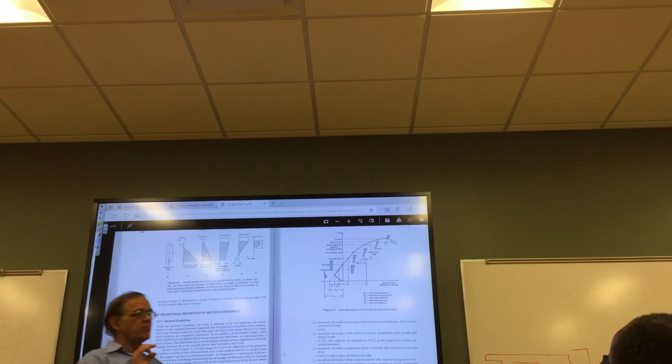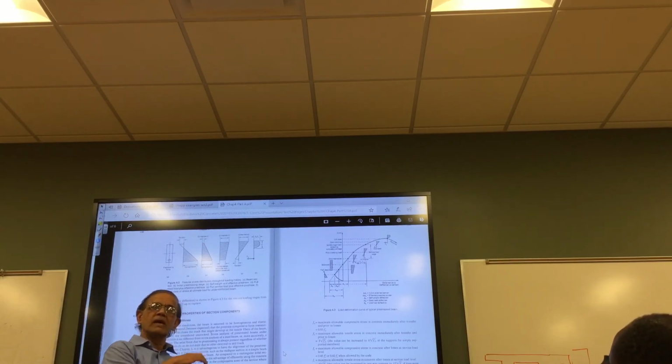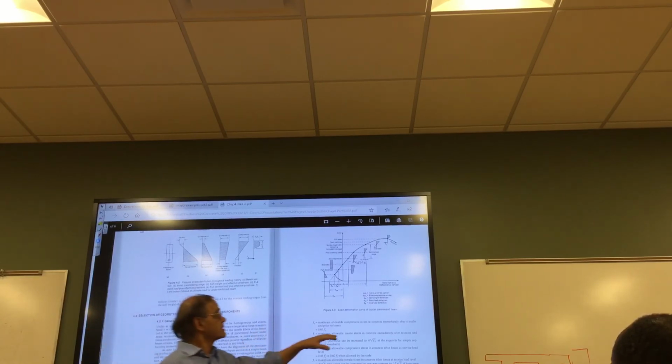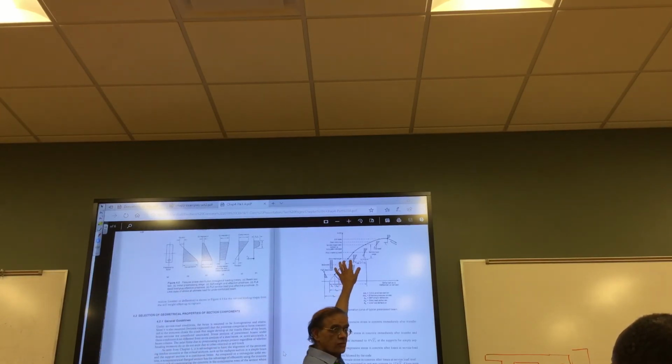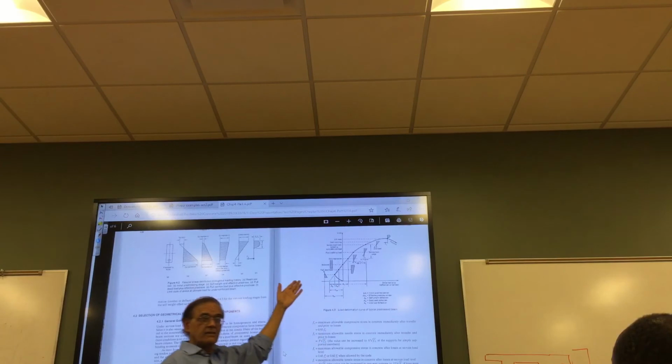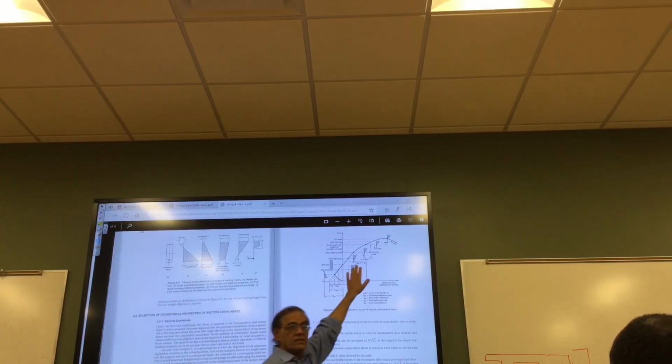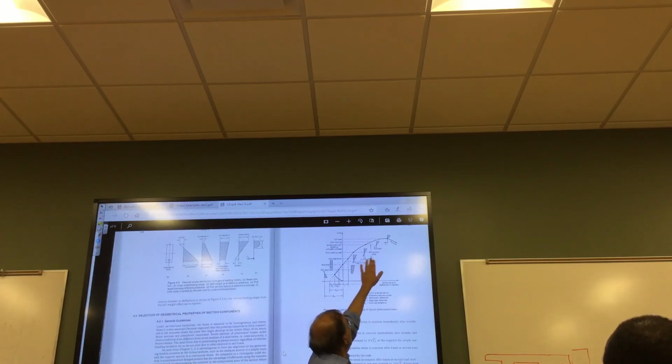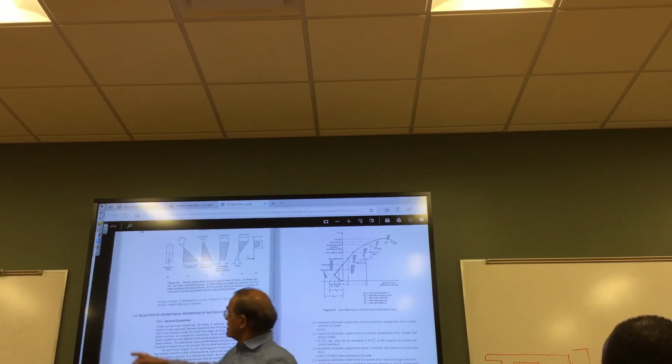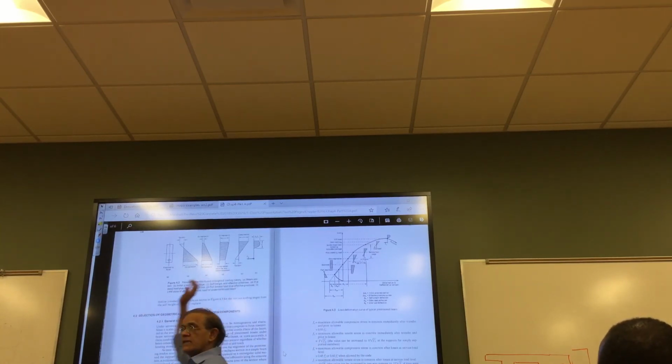There is also the balanced part, where you're balancing the pre-stress load with the external load. Remember the load balancing method? That's this one here. Beyond that, you will start tensioning to some extent, and then finally the last part we saw here, and your deflection keeps on increasing.